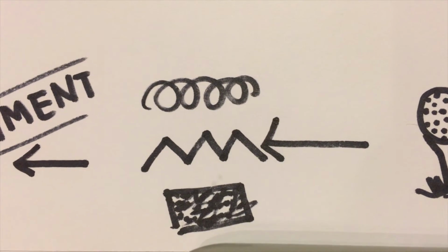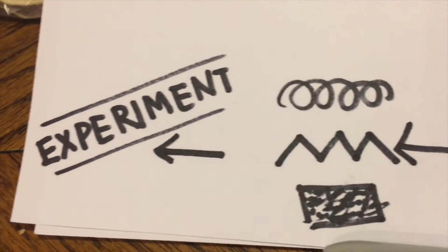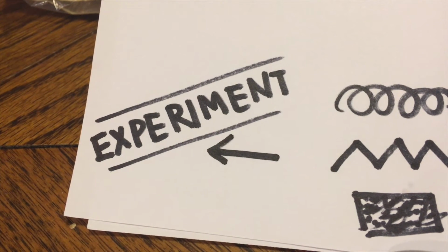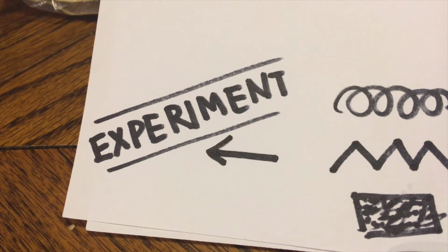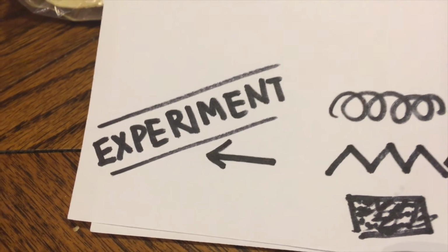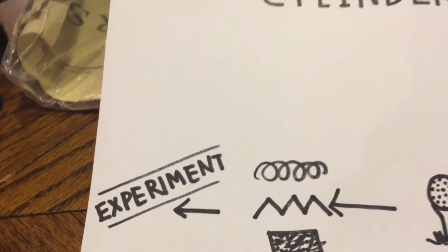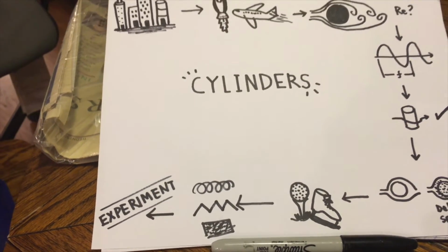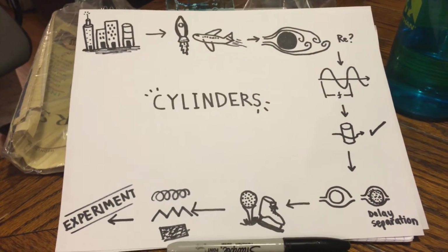The hypothesis that was proposed for this lab was that inducing a turbulent boundary layer would delay the separation point of the flow over the cylinder. This separation can be seen visually, as well as through the pressure data acquired during the experiment. Comparing the tripped and untripped flow around the cylinder, the tripped flow should have a higher average pressure reading towards the back of the body.